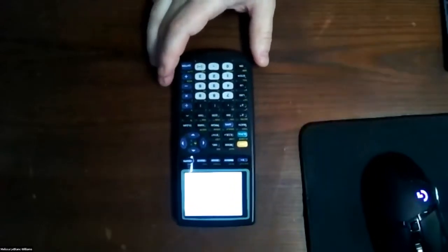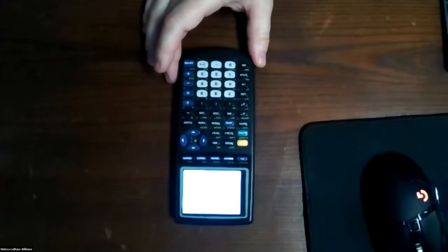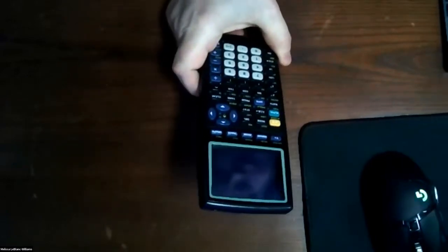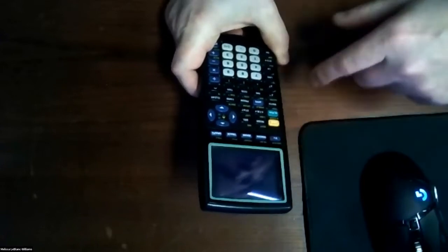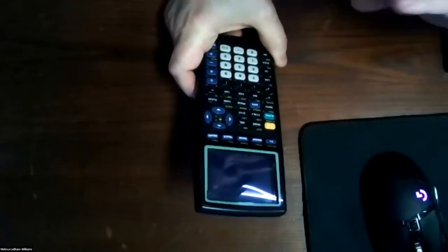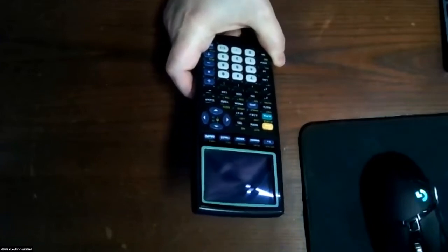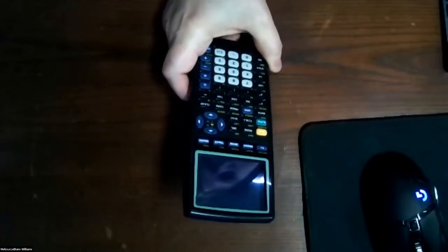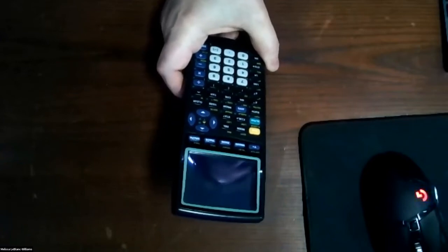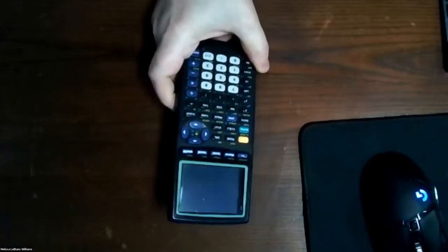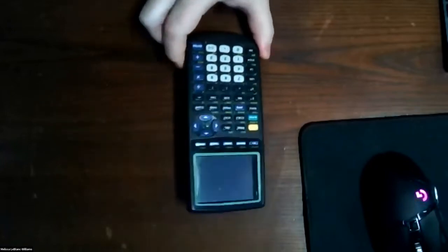It's starting up. It actually is running an old version of Raspberry Pi OS on here. This is actually the project that kind of got me started with working with Adafruit, because I could not get the screen working with the Raspberry Pi Zero, and I finally had to really dig into the Linux internals to figure out the issue. I remember it ended up being something along the lines of adding a module to the etc modules file to get it to start up correctly.